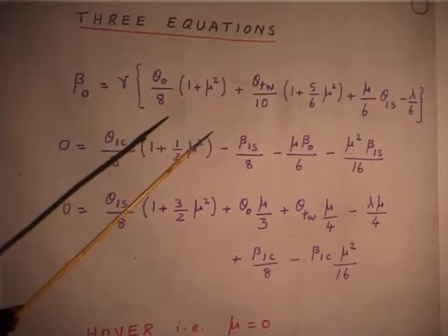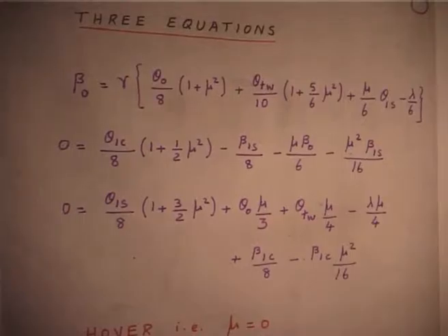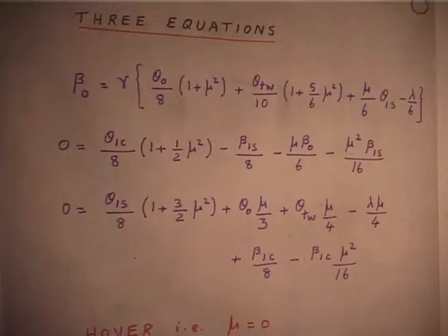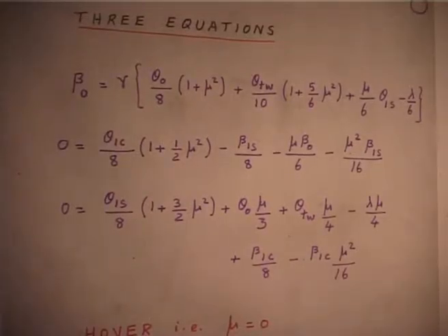what is the input pitch angle, what is the operating condition, at least that part you must know, because if I do not know that, then what will I do, that part we will come to later. That is what the trim analysis is. The entire trim analysis is related to iterating between flap motion and then fuselage equilibrium. So, you have to keep going back and forth, that is why it is a complicated analysis, okay. Even the solution procedure is a little complicated. This is the very simplest, that is what I am showing.